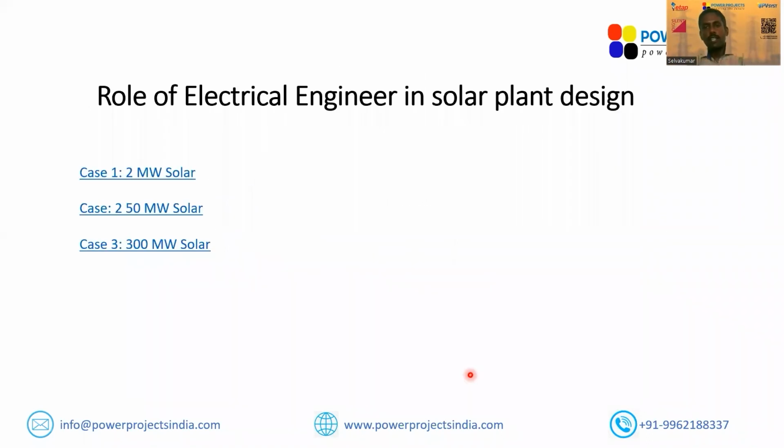So what's the role of an engineer in solar plant design? When you are designing a solar plant, you need to look at quite a lot of aspects. One, the impact of this solar plant on the grid. The second aspect is the impact of the grid on the solar plant. And you need to work towards minimizing the capital investment, enhancing the energy produced, and optimizing the levelized cost of energy for 25 years, which is typically the lifetime of the solar plant.